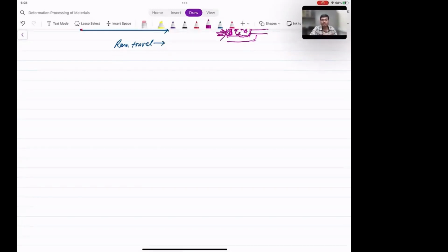If we measure the pressure by the cross section of the tool or the component of the machine which is in contact with the material, that pressure will be different than the pressure experienced by the material. The pressure experienced by the material depends on the cross section of that material or component itself.